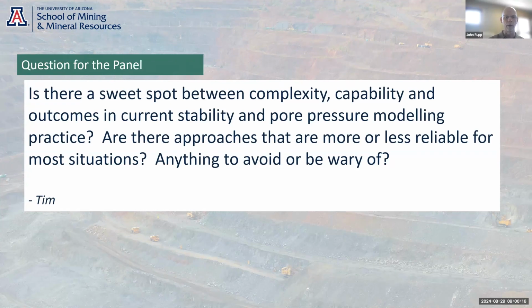I didn't put this in the answer, I kept it pretty brief, but make sure you don't let the model cloud your understanding of the hydrogeology. You've got to be using your understanding to check that the model is right. You need to have a good feeling of what the answer is, or what the range of answers should be, rather than relying on the model to tell you what it is. So it's just keeping things simple and only modeling what you need to and not more than that.